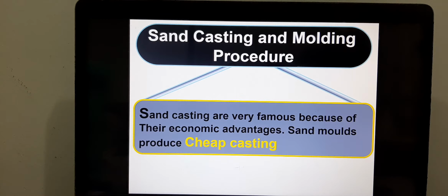So your task is basically, you need to be a professional to actually construct the mold well from the silica sand. And if you constructed the mold well, your other cost would be the wood pattern, which is very minimal, the pattern which is made out of wood. And lastly would be the metal itself, where you're going to melt it and pour it into the mold cavity. But besides that, there are no other hidden costs when you're using sand casting as a manufacturing technique.